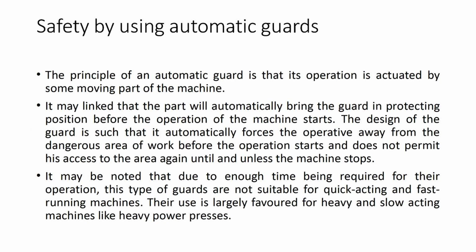And finally, safety by using automatic guards. The operation of an automatic guard is actuated by some moving part of the machine. It's linked so that it automatically brings the guard into the protecting position before the machine operation starts. The design is brilliant. It automatically forces the operative away from the dangerous area before the operation starts and does not permit access again unless the machine stops.